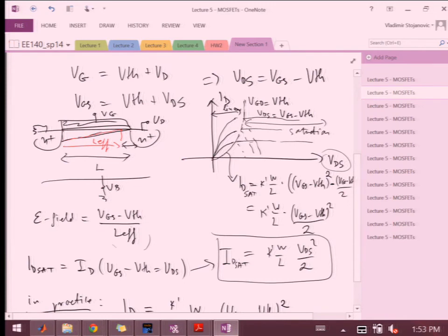Now, if you look at this picture over here, this was L effective, but it was retreating back because this piece here was the increase in the depletion of this drain. If I increase VD, the depletion region goes into the P, because this is highly doped, nothing really happens on the drain side. Most of the depletion region forms on the, yeah?